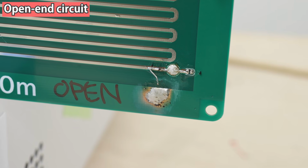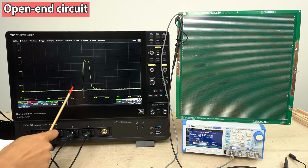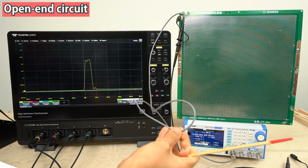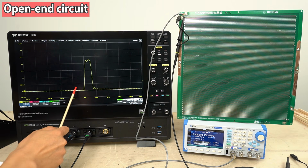First, let's try the circuit with the end left open. You can see that the waveform rises a bit slowly. This could be caused by losses in the cable carrying the pulse voltage or by inductance and capacitance in the circuit.